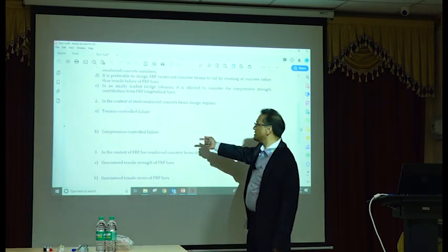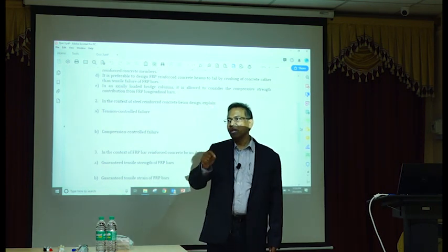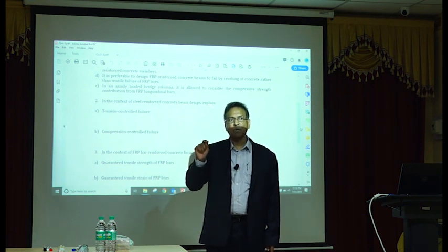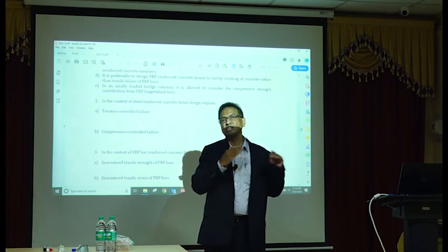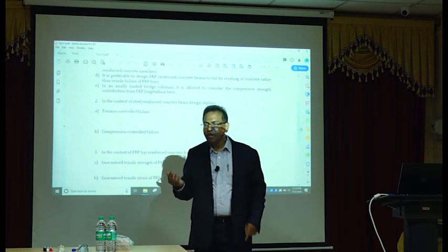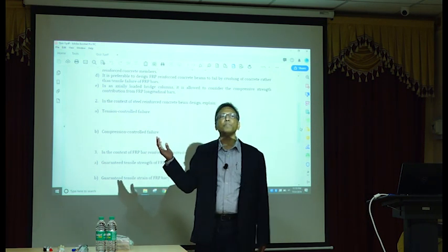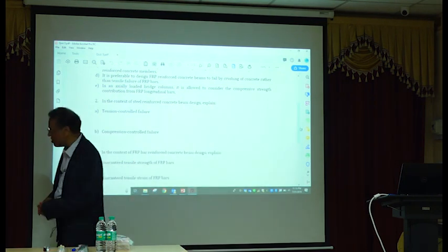So in case of compression control failure, the strain is less than or equal to the yield strain of the bars. That's what will classify a member to be compression control. In regular beams, we will never design a compression control beam. The reason for that is why? Do you remember?